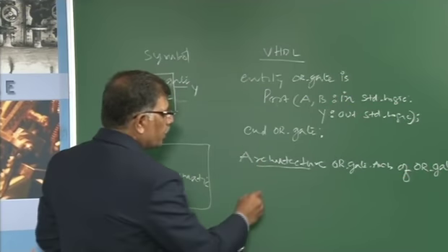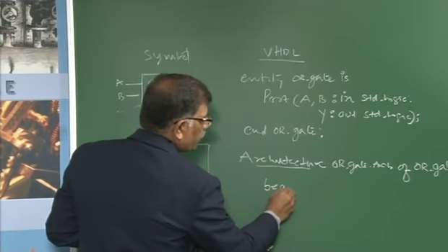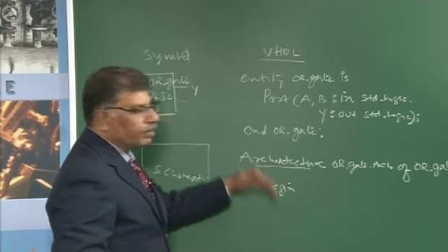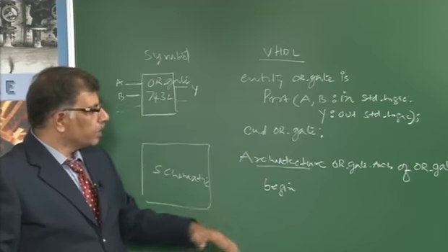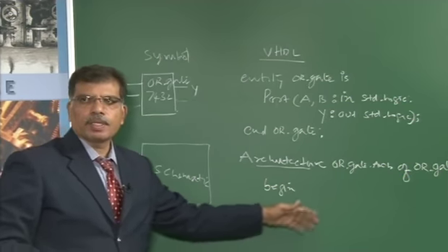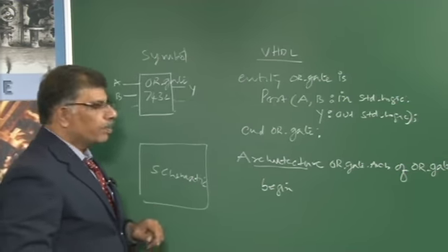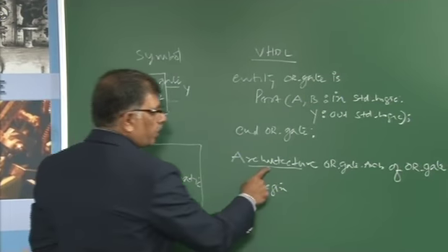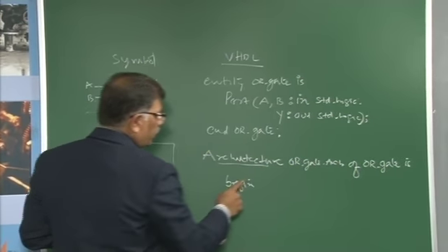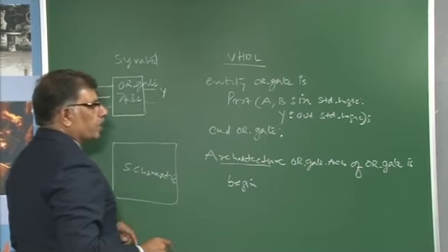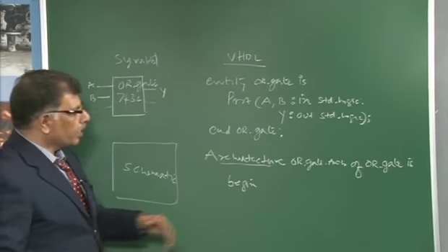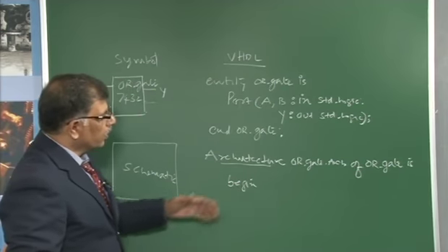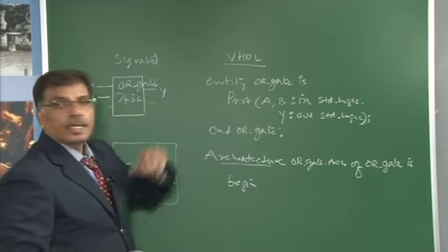So you have a declarative part here, which we will see in detail in later classes. I am just writing how the HDL language can be written for a simple OR gate. Then we will see what all the different features are and how best you can utilize them to represent bigger circuitry. After writing this line, next you will have a begin. Next you have to write concurrent statements, in the sense that I have to define the functionality of this entity.